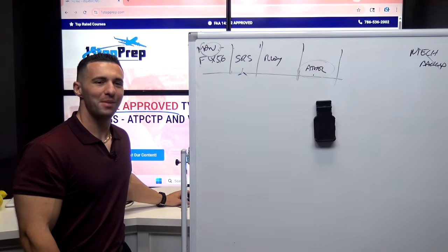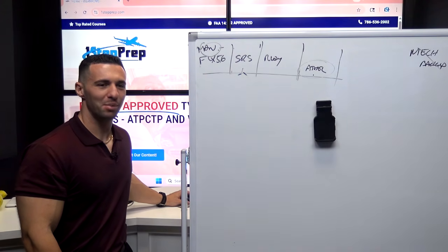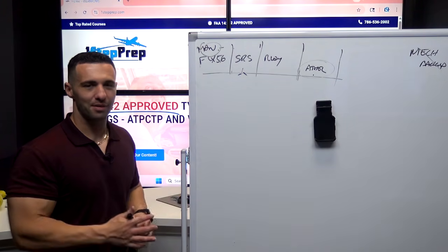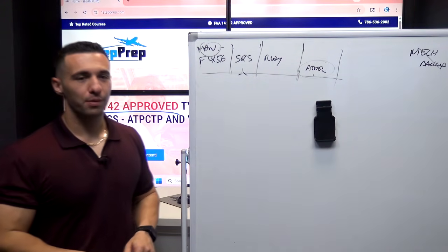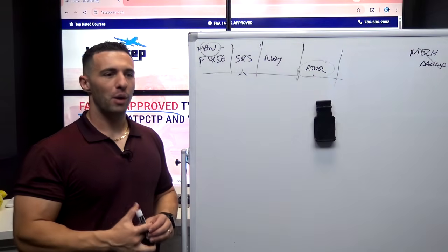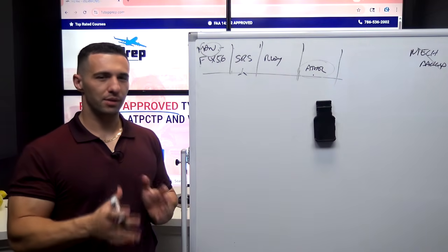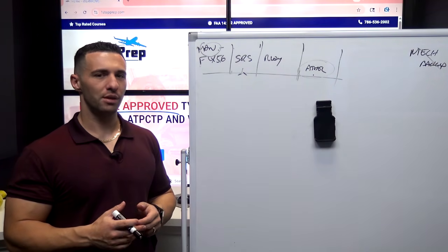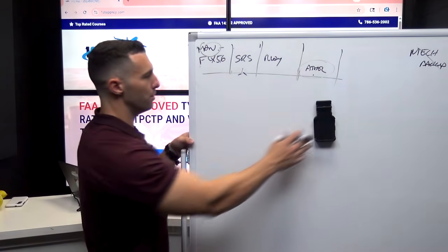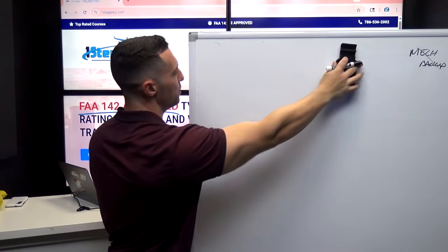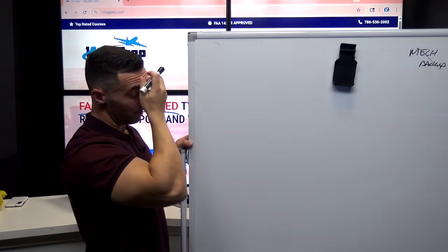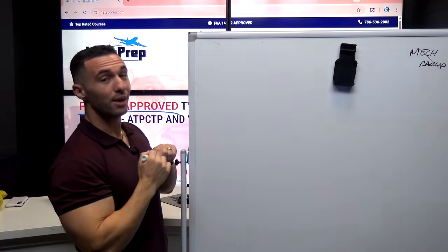I would say for me, my favorite configuration in this plane is flaps 2, speed 170. This is really, really helpful from an energy management perspective. I don't know how many of you on here are relatively new to flying the 320, but I will share with you that, like any jet, the 320 is no exception to this. It does not go down and slow down very well.